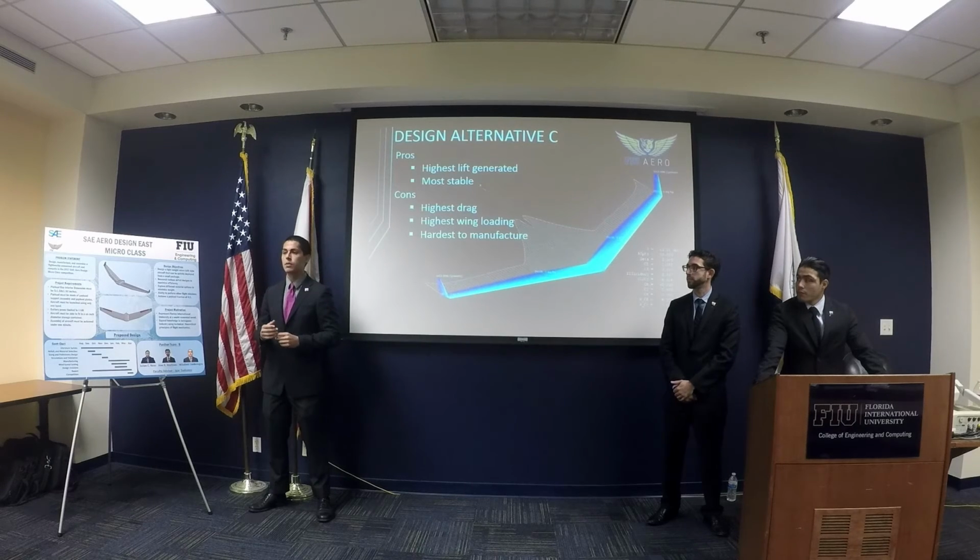It comes at a cost of the coefficient of lift being affected, but that can be counteracted by a bigger motor or a bigger propeller to generate more power. But yeah, we thought it was a good challenge. Conventional aircraft design is fun and all, but we did not see the challenge in that. We saw a challenge in this.